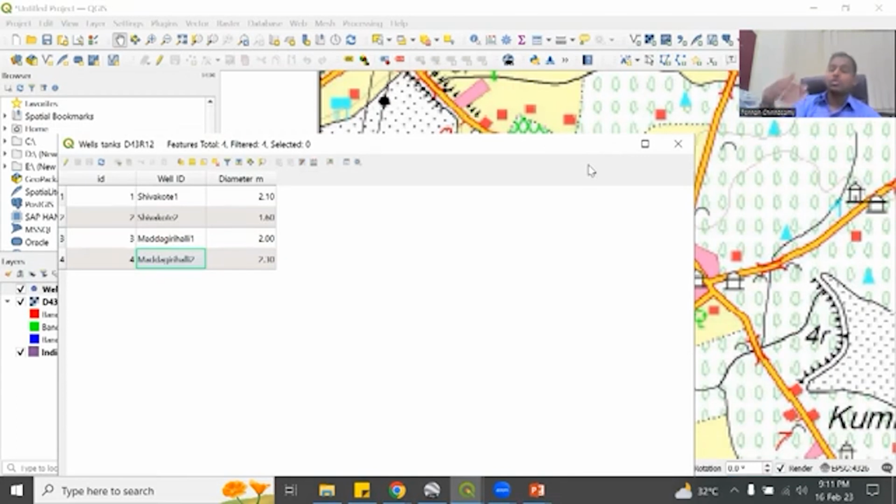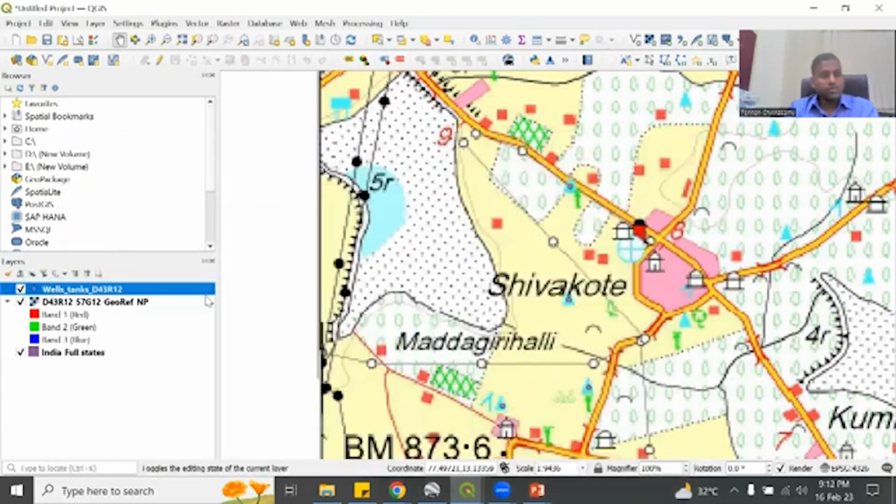So this is the same thing you'll do for a drone image, a photograph image, and this is the image that you've taken from a paper map. First thing is to make sure the images are georeferenced. Most of the images are georeferenced, so you don't have to worry if it is from the drone or a GPS handheld camera, but scanned images like this need to be georeferenced. Okay, so this is the first step.